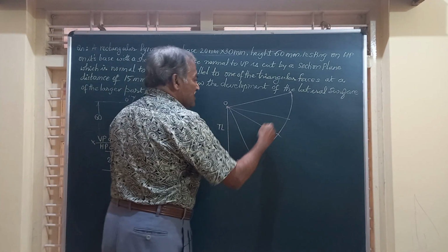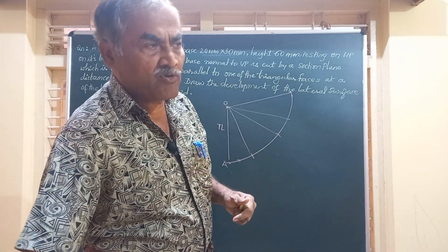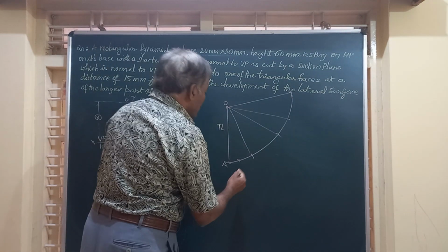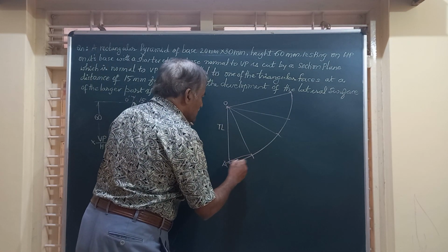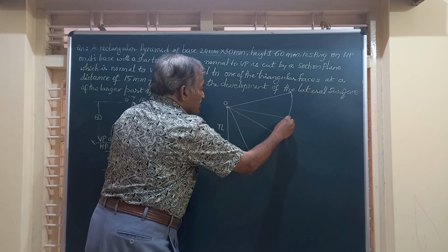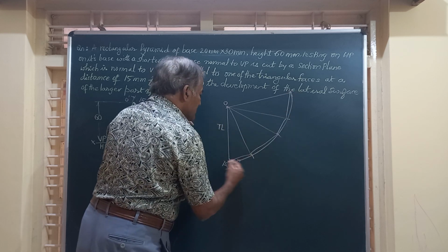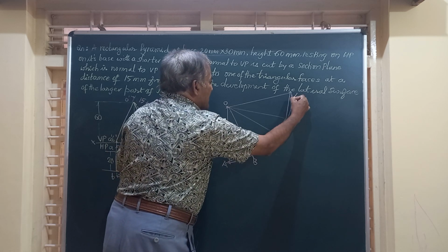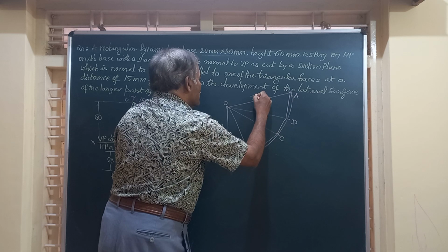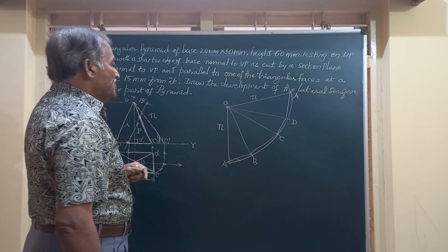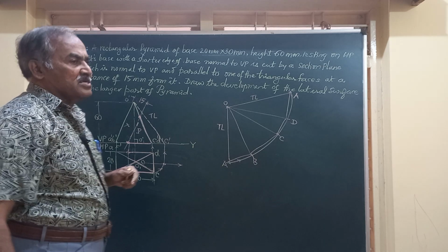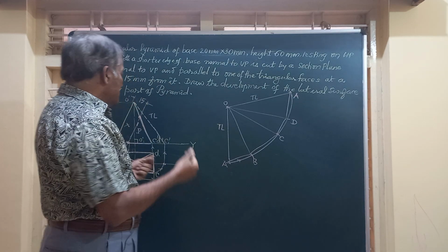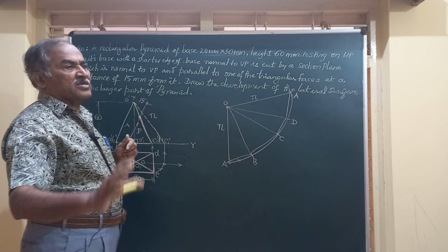And very obviously, the base of the pyramid will have all straight edges, all the base edges are straight. So I am going to join that, join here, join this, and join this. So A is the starting point, then comes B, C, D, and A. This length OA is also equal to the true length. Friends, we have drawn the development assuming it is not cut by any section plane. Now, considering this section plane, let us see where all it is cutting.